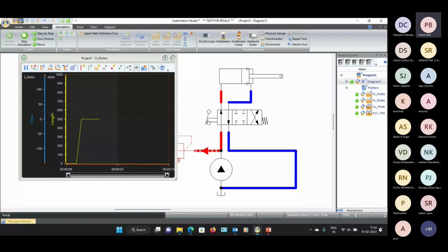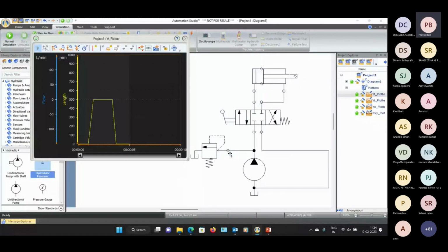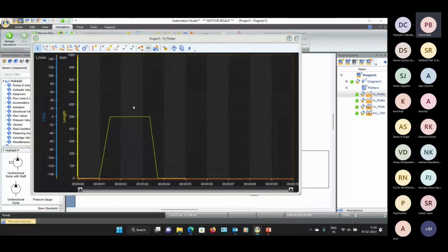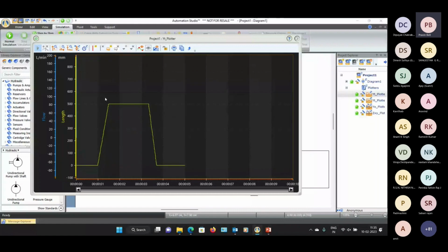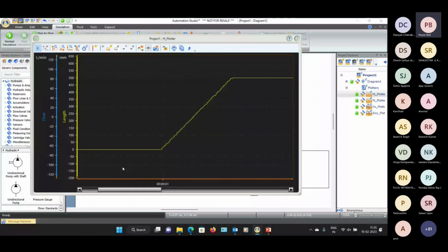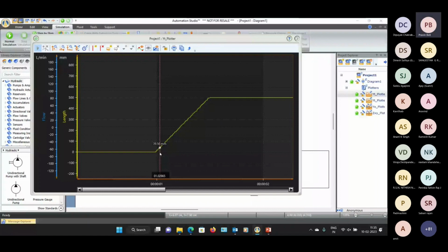And immediately I can see my waveforms here. Now this plotter is very flexible. For example, I can hold this axis and move it up and down. Then I can zoom into any area. I can also put these marker points because these are important to take measurements. When I put two marker points here, it shows me delta T is equal to 0.5 seconds.